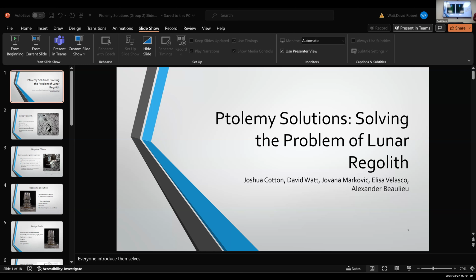With that in mind, we decided to assume, given that the depth of a footprint for someone on the moon was about 5 to 7 centimeters, we're taking about 7 centimeters deep, plots of 3 by 3. That total mass of lunar regolith, which would then be seen up to the windows of the lander, is about 1890 kilograms.